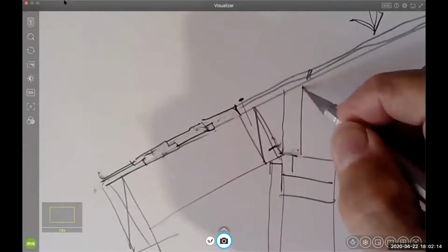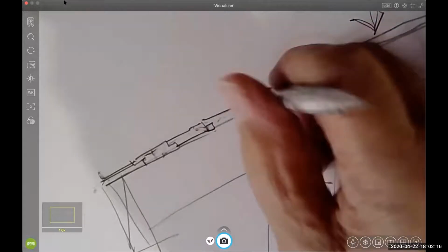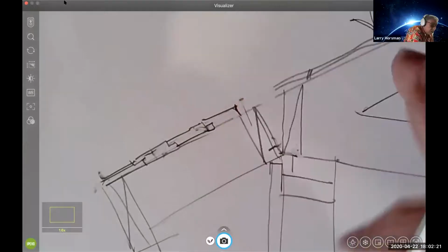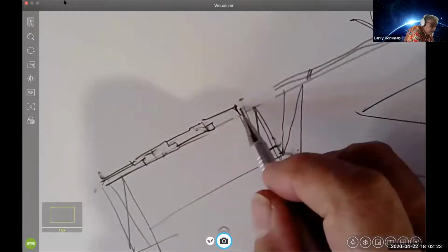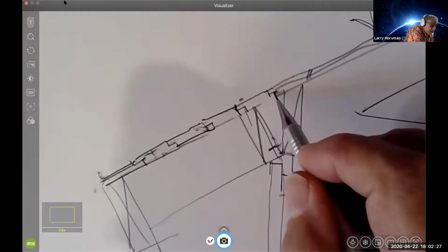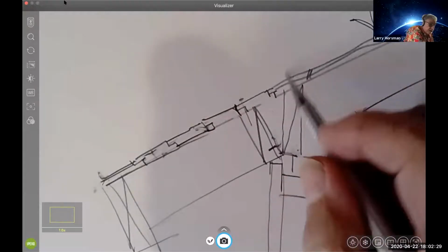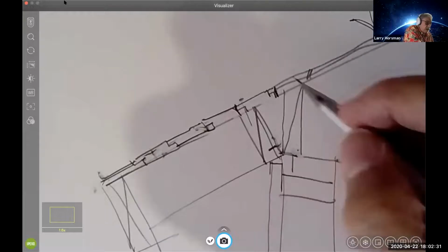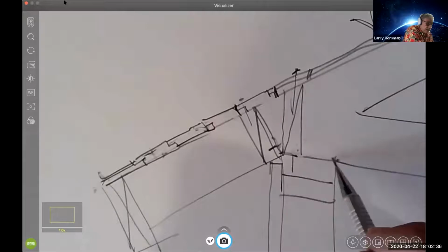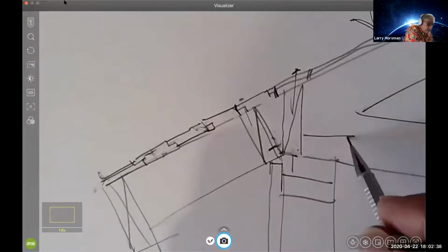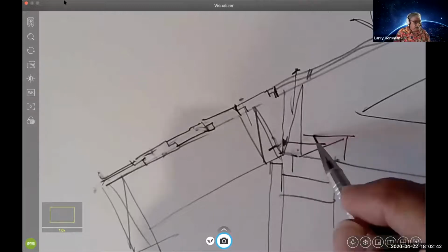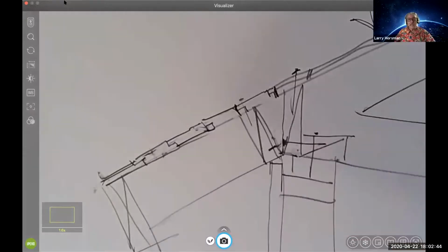A bevel, huh? Yeah, there it is. So this is just acting as a stucco stop. And they would just run this up so you could do your shear transfer here. You can put a clip in there, or you could also put a block in there and nail. So either a clip or the blocking, although you have to make sure this isn't installed.